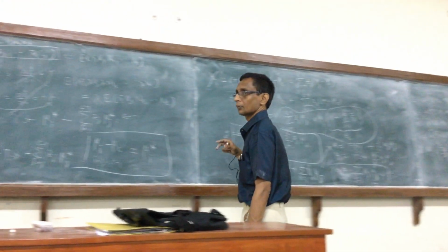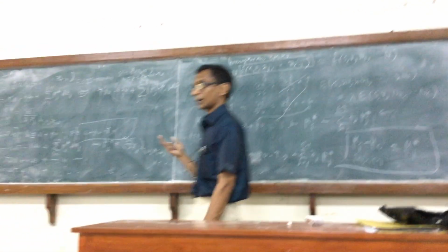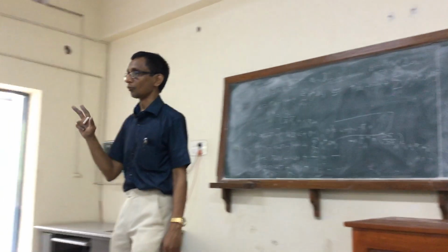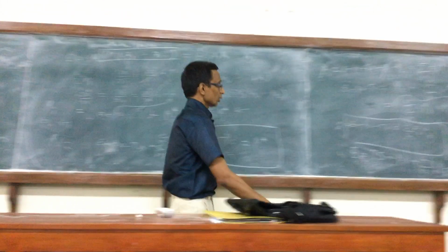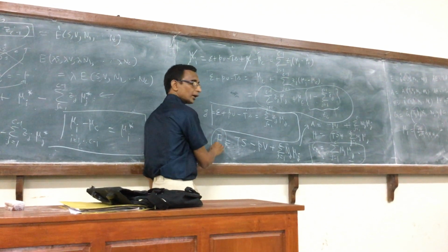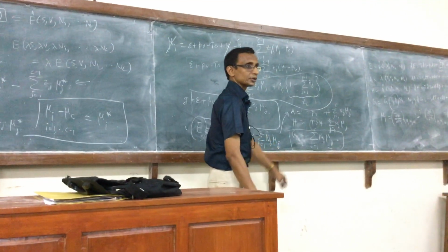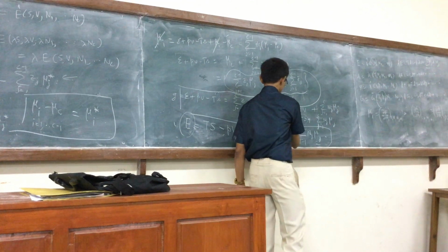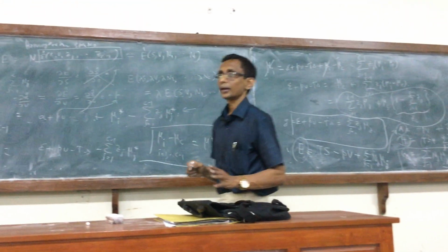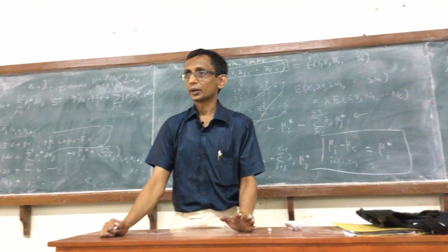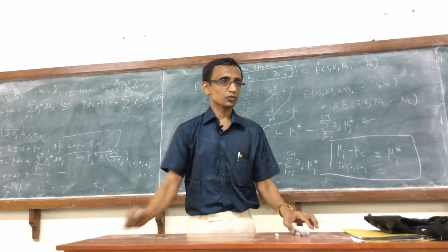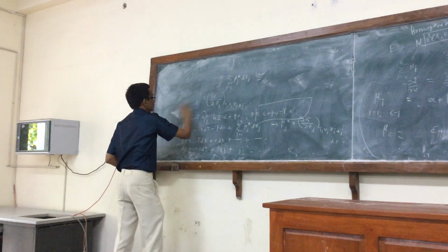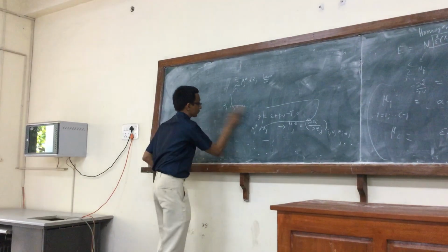is that, because we want to have everything in compact form, and temperature and pressure are natural variables, I mean more natural for engineers than for physicists. So you can ask, can I obtain a similar compact expression for these other quantities, or in fact for that matter any extensive property, right? The answer to that is in the form of another very important quantity that is introduced in many of the textbooks, which is the partial molar property associated with an extensive variable.